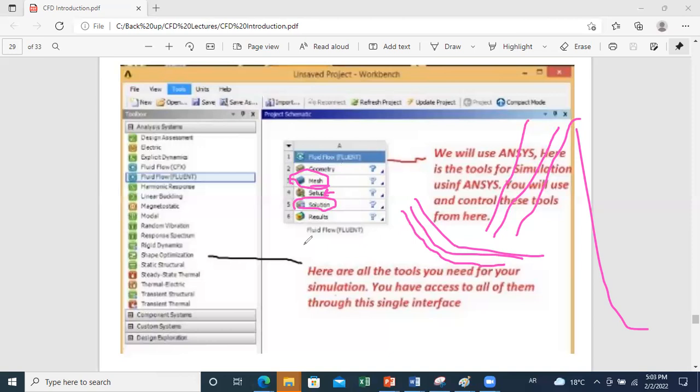Fluent. Okay. And once I have a converged solution, I can explore the results here. I can create the plots I want. I can extract numbers, so I can compute, for example, the average temperature in a certain plane. I can create a plane and find the average temperature or velocity in this plane, for example. I can see profiles. So I can do a lot of things in the results section. Okay, so this is overall the different steps that I will use in ANSYS Fluent.